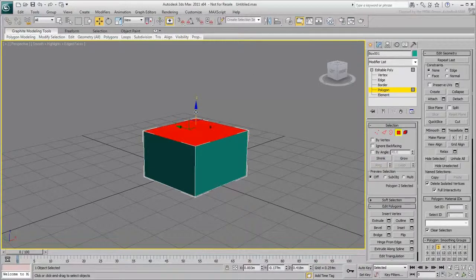The edge between two vertices is always perfectly straight. To curve or bend a surface, you must add more detail by subdividing the polygons. You can subdivide your object in a number of ways. Let's start at the polygon sub-object level.